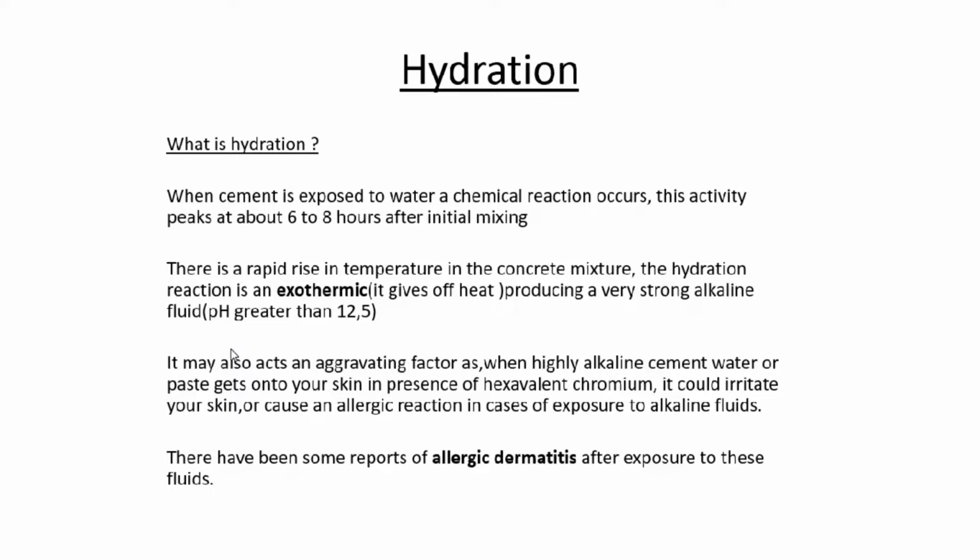Talking about the allergies, what are the dangers of working with cement? It causes allergic dermatitis, which can peel the skin off your hands. So it is not very advisable to touch cement or concrete when you are working with such components.